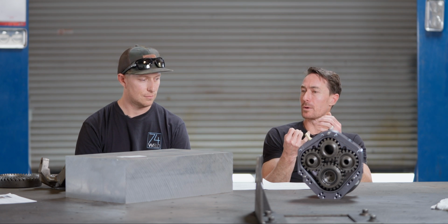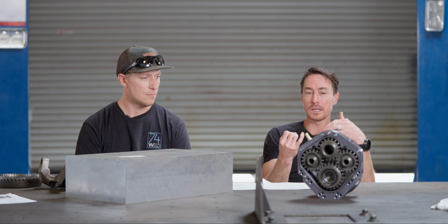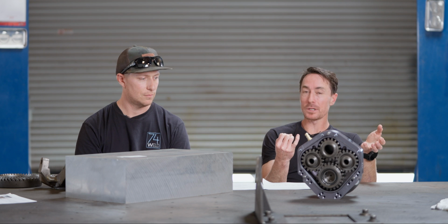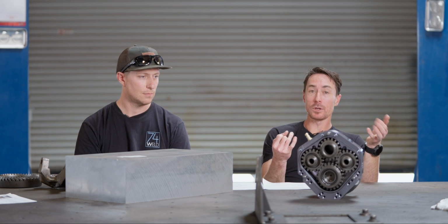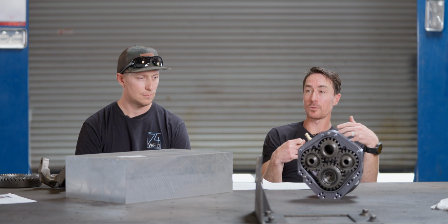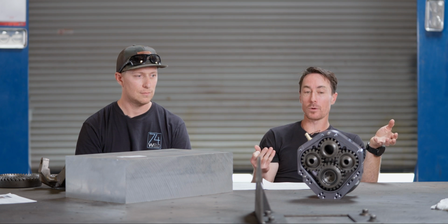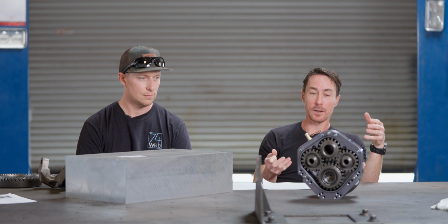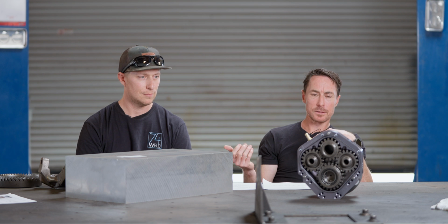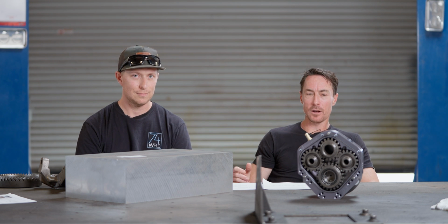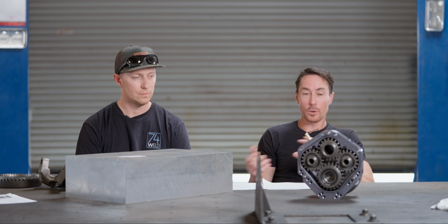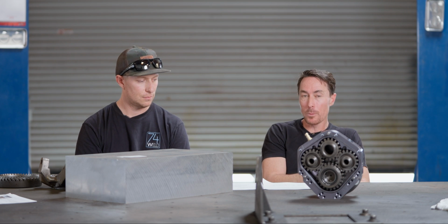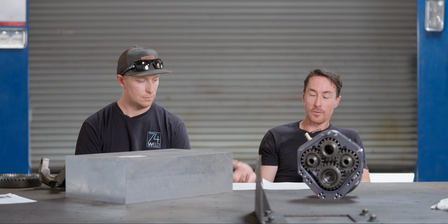I don't know specifically what it was. It didn't have good thermal properties, and maybe they would get so hot that they would cook seals at certain RPMs. So there was a notion that you can't drive portals for long distances on the highway. And we kind of scratch our head on that and go, well, we have no problem with that. And I think part of that is the thermal properties of aluminum are so much better than of iron.